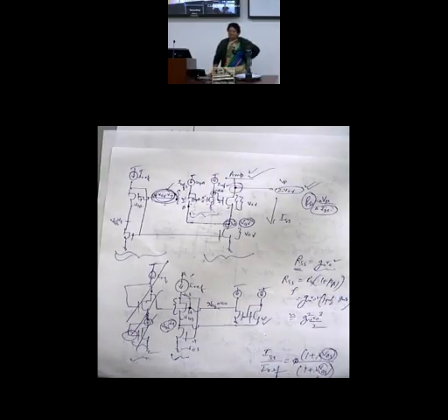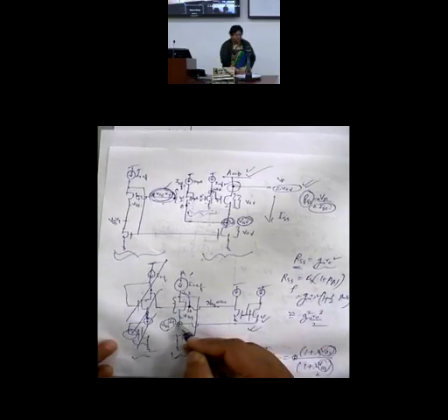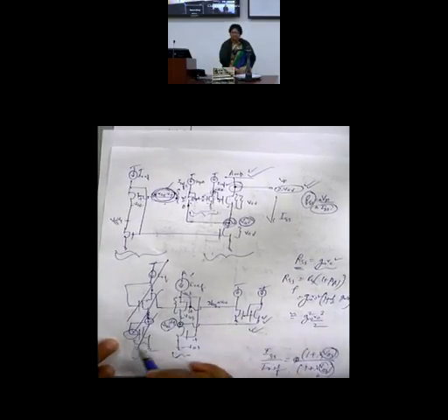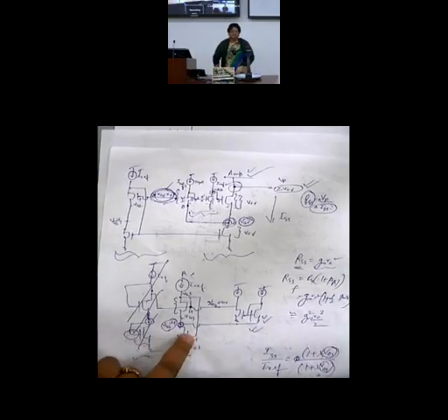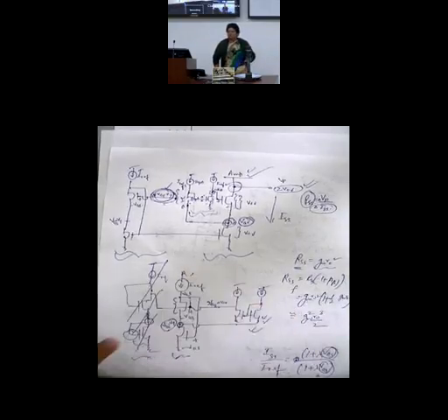As far as possible, the reference arm and the bias arm should have the same parameters, so that when you mirror, there should be no degradation of the current because of the lambda effect. If I go for this solution, I can have this node at 1 V overdrive. If I go for this solution, possibly I may not. This may influence the circuitry. Otherwise, if there is no solution, go for this.